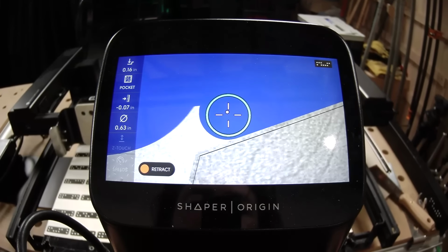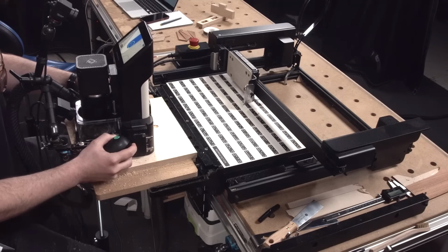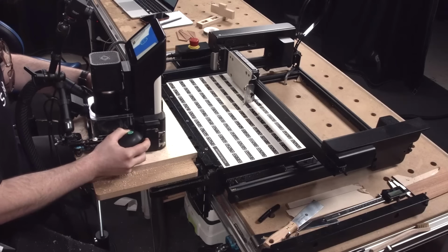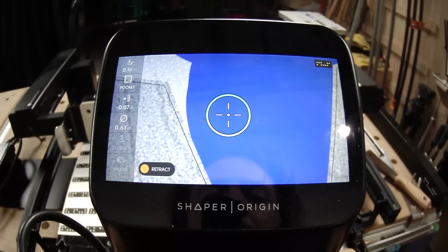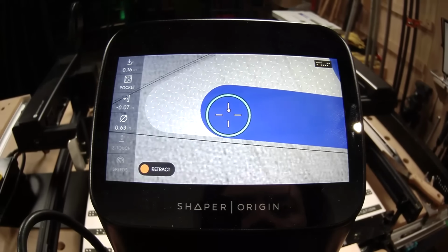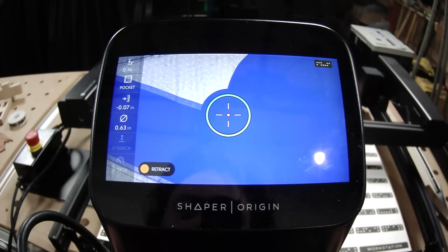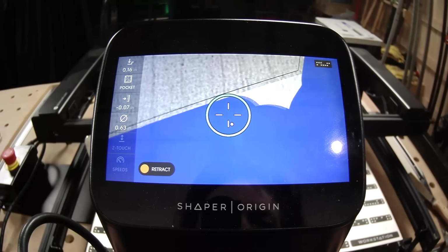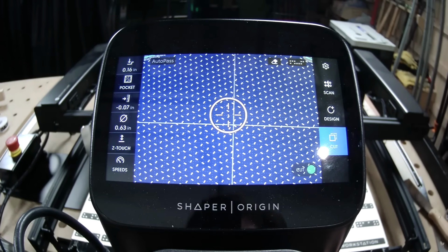And after Jake is done with this cut, with the 16 millimeter bit, I think he said he's going to switch to that 1/8 inch and clear out just those little tiny corners. And for now, he'll probably start with either 0 offset or a very small negative offset so that all of the parts fit. And I'm excited to see if all these parts that we've cut already are going to fit nicely into the star shape as is, or if we're going to have to add just a little bit of offset, which of course is super easy to do with Origin.